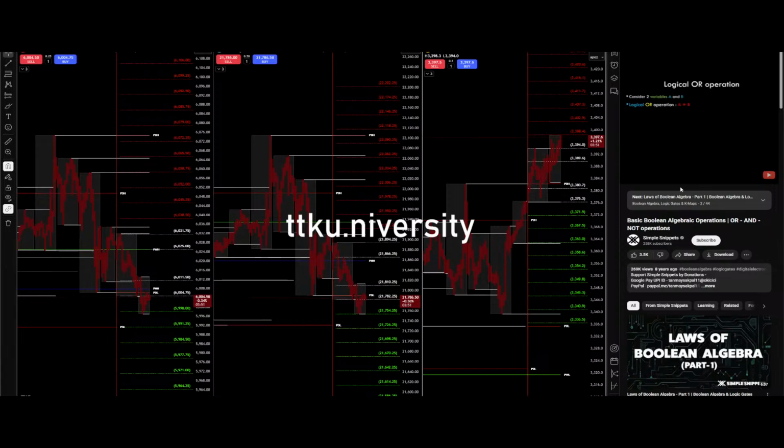Now the plus sign here is pronounced as OR because it is a logical OR operation and not a typical addition. So consider case 1. We take the values of A and B as 0 and 0. Now the OR operation between 0 or 0 is equal to 0. Consider case 2. Here we consider B's value as 1. Now the logical OR operation works similar to the addition operation. So 0 or 1 is equal to 1.